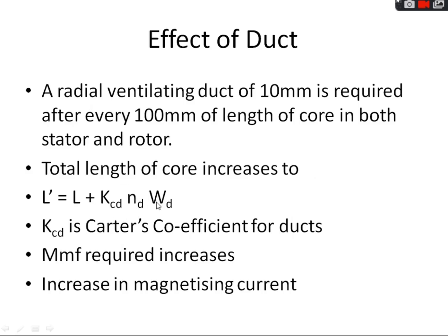If I assume that the length of the core is, let's say, 300 mm, then I will require a minimum of 2 ducts with 10 mm thickness. So definitely the ducts will increase the overall length of the motor.